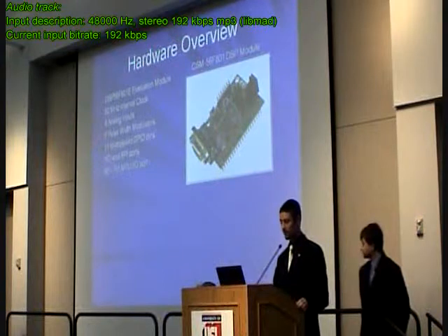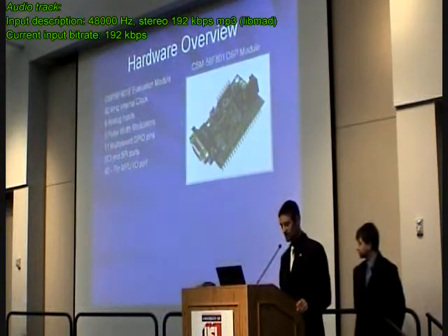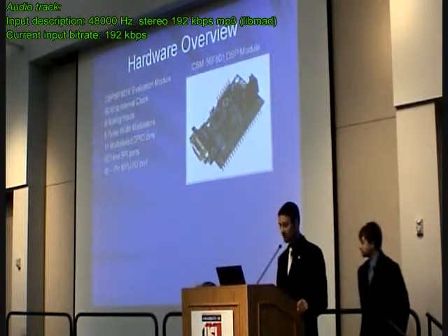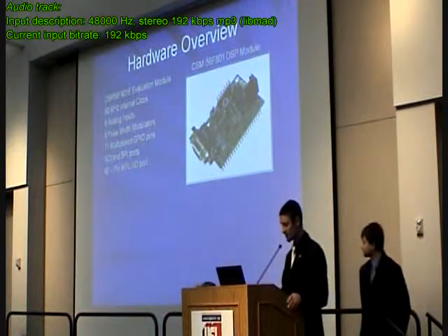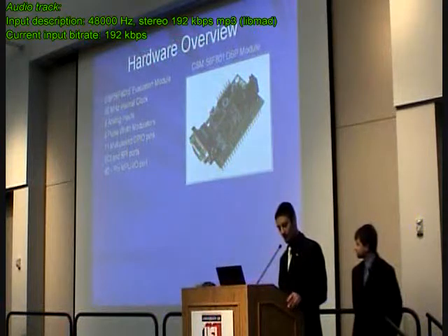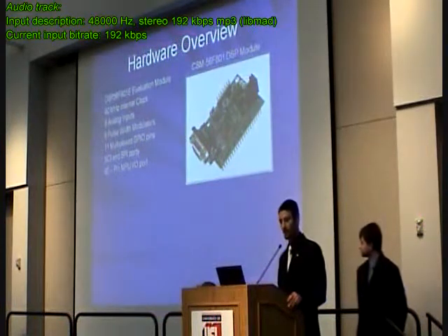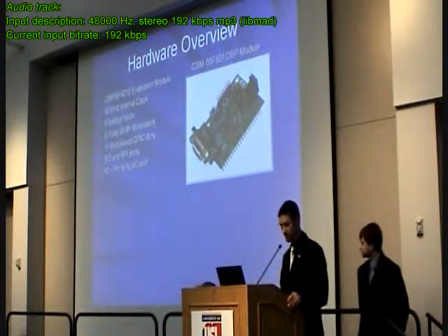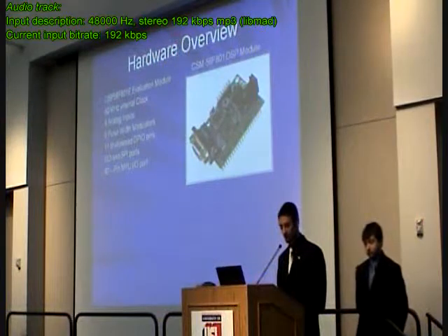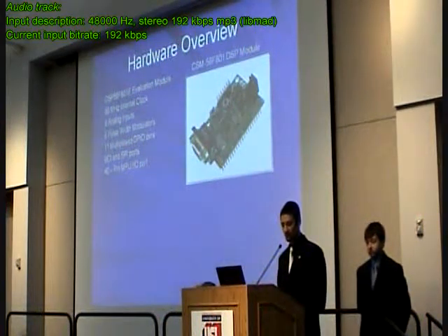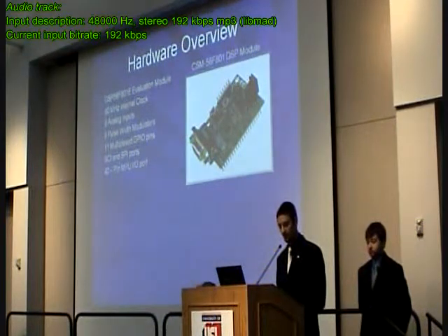So the DSP model that we chose for our project is the DSP56F801 Evaluation Development Board. This particular model has a 16-bit processor with a 60 megahertz internal clock. It is equipped with several analog input channels and 11 general use input-output pins. A major drawback to this particular board is its lack of a digital to analog converter to reconstruct the output signal.